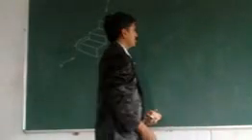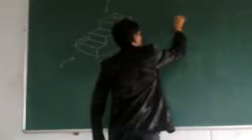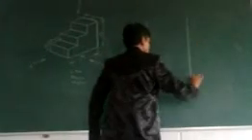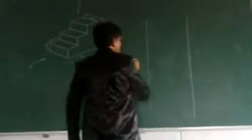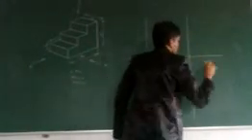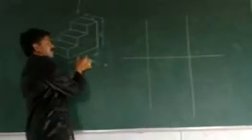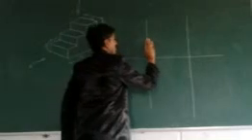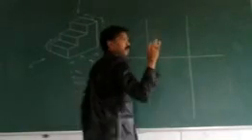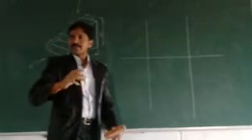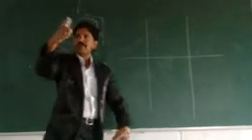See one more piece of information for you. When we draw these plane spaces, they should be larger than the dimension of the object. For example, see here, it is 90. The space from this line to this line is more than 120, because space is required for dimensions after the representation of the view.